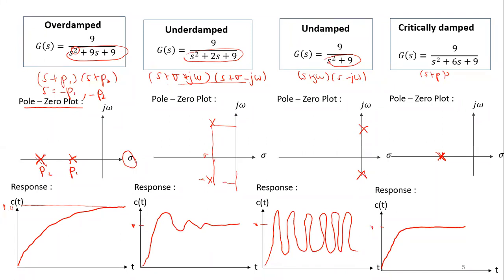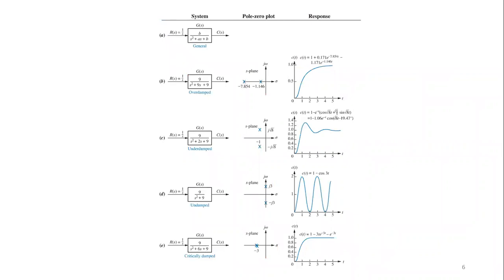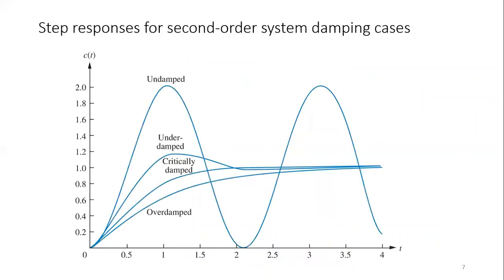This is the worst thing that we as control engineers don't want to happen. What it means here is that from 0 to 90 degree, it will move, but it oscillates between, for example, 100 to 80 degree. So these are things that we avoid. For critically damped, usually this is an ideal system. The whole thing that I explained is actually in table 4.7, figure 4.7 that you can see here. Okay, so next one.